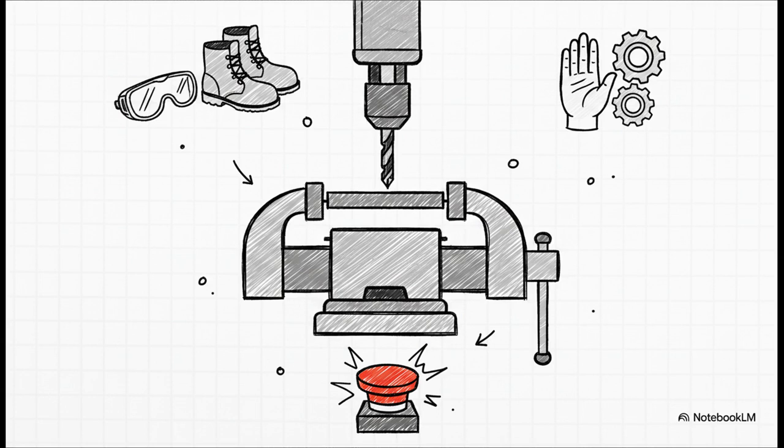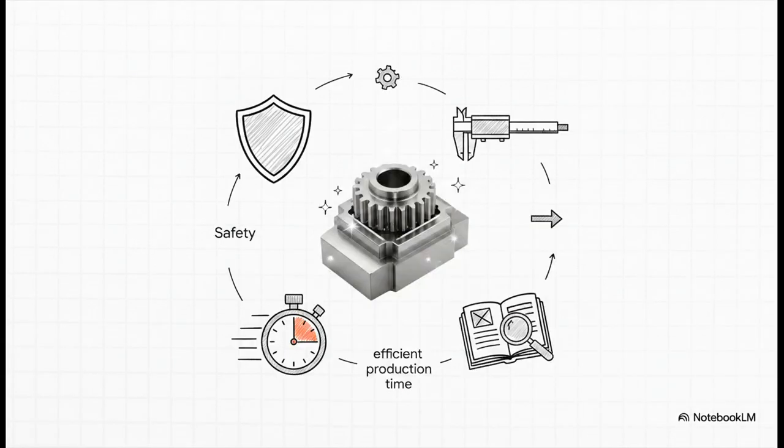And remember this above all else: if you hear an abnormal noise, I'm talking a screech, a shudder, or some heavy vibration, hit that emergency stop immediately. Always follow your workshop's specific safety rules, no exceptions. To summarize our core takeaway for today, proper parameter setting is the master key that unlocks everything else. It's exactly what guarantees dimensional accuracy, your own operator safety, a beautiful surface finish on the final part, and highly